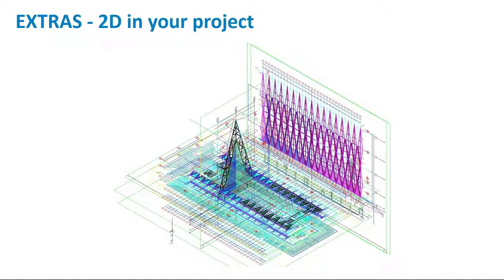So you could literally lose the DWGs, you could delete them off your system, you could open up the Revit model and still see the DWGs there. They're just saying that the link's been lost. So it keeps a cached copy. What that means is you can store this Revit file that has DWGs linked in on Revit Server or C4R, and it's got DWGs on it.